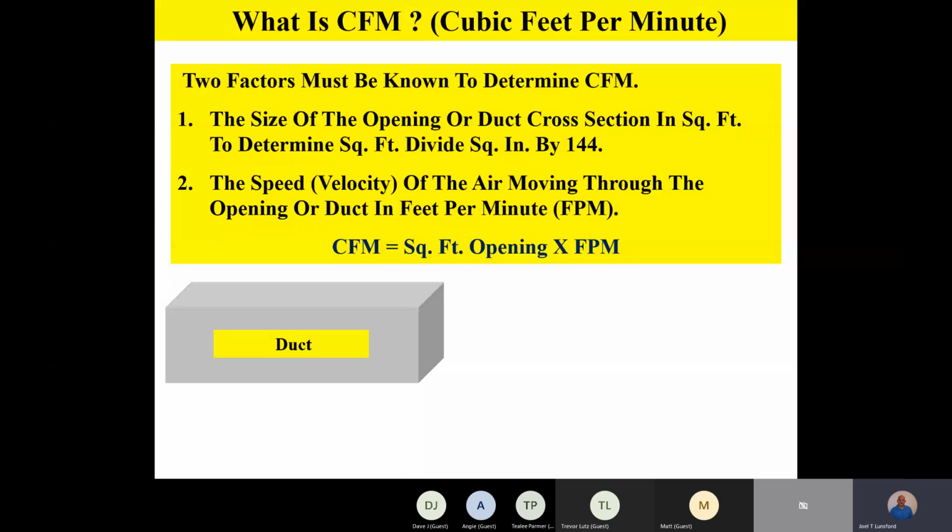So if you take a look at that air duct calculator, let's say, for instance, in our example, just looking at the PowerPoint to make it simple, we lined up 1,000 CFM at 1,000 feet a minute velocity, in our example where 1M and 1M line up there. So we find out that if we have 1,000 CFM at 1,000 foot a minute velocity, which is pretty fast, that would require about a 13-inch duct, something like that.